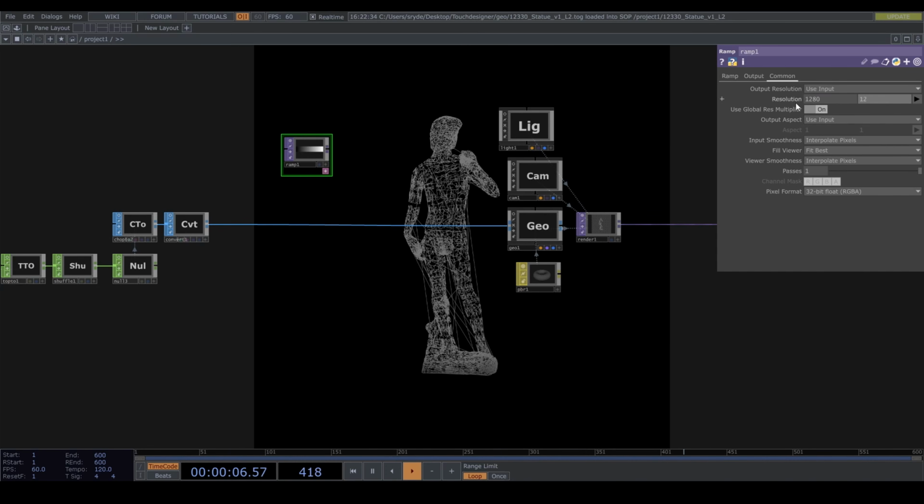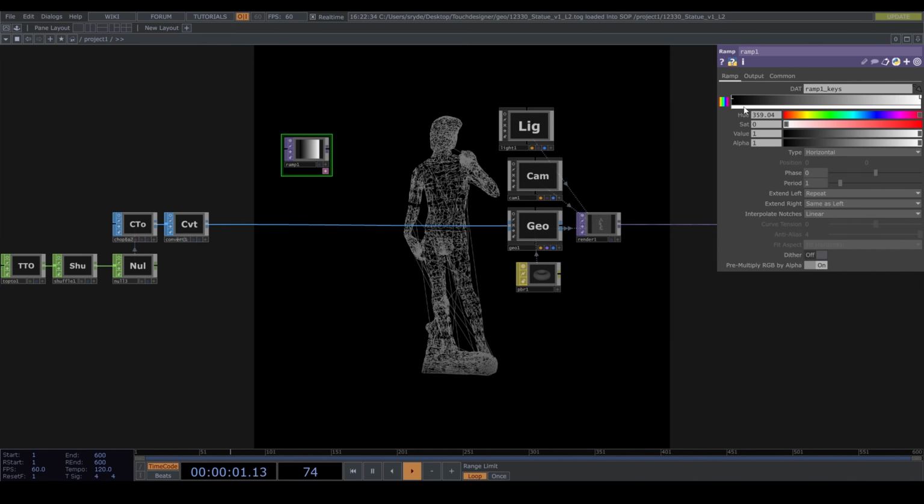The environment map uses an image to illuminate your material. It's really powerful to create realistic lights and materials. But you can also just use the artificial lights provided by TouchDesigner. Play around with it until it's pretty, but not too intense on your machine, so it still runs in real time.